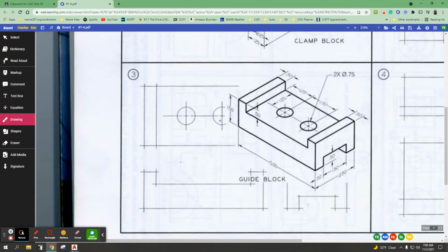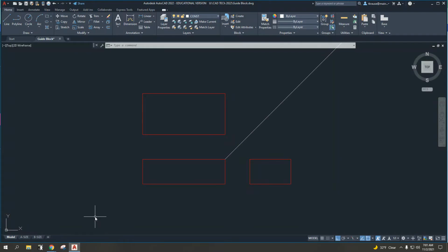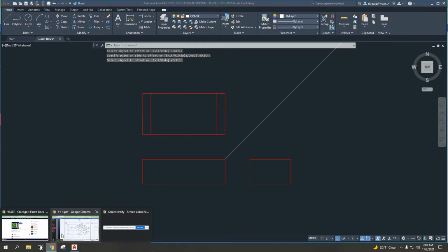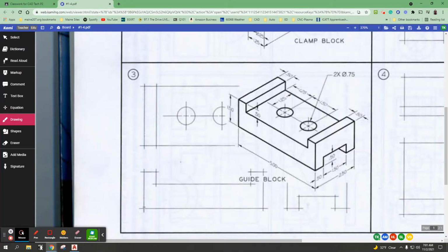After that, I would probably start with the center of the circles. The best view for that is going to be this top view. So I'm going to offset a half inch over, then 1.25, and then 1.5. So a half inch, 0.5, 1.25, offset 0.5. And actually that's this end in, and actually this one at the same time. Then we'll go back, and we'll do a 1.25.